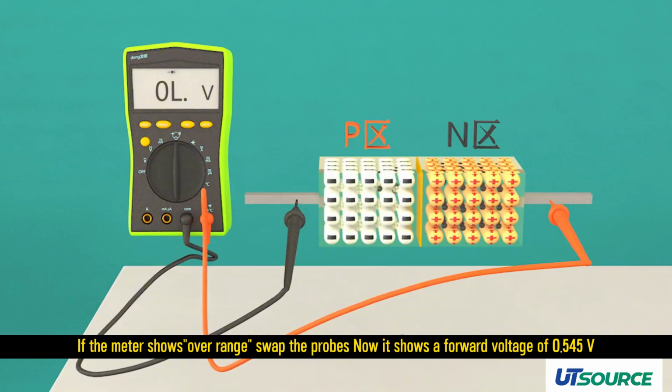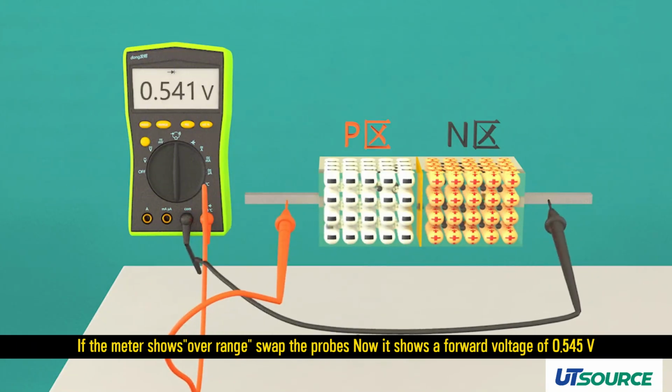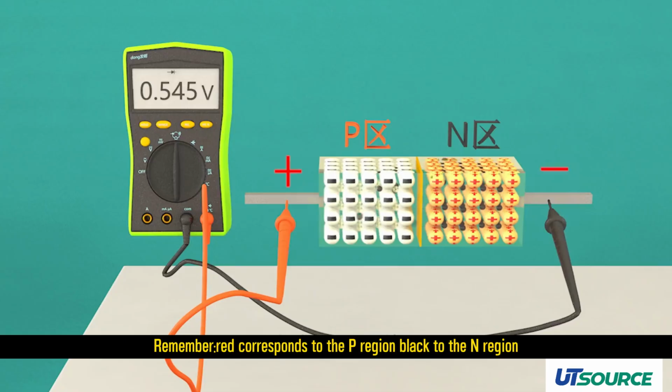Now it shows a forward voltage of 0.545 volt. That means the red probe is on the anode and the black probe on the cathode. Remember, red corresponds to the P region, black to the N region.